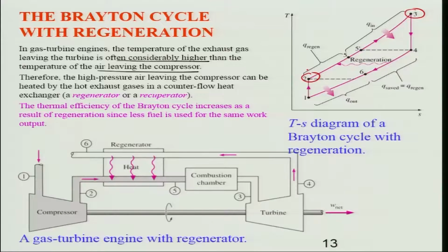In that case, what we can do is heat the gas which comes out of the compressor using the heat of the exhaust gases, by making use of a counterflow heat exchanger. This particular way of heating the gas from the compressor by the exhaust gas in a counterflow heat exchanger is called a regenerator. So this is the schematic diagram of it.